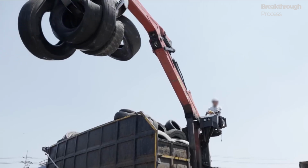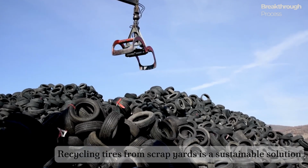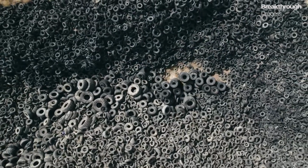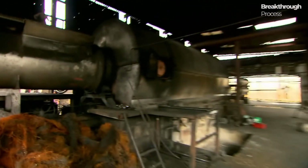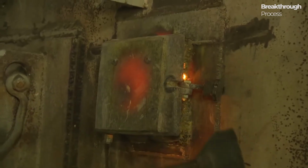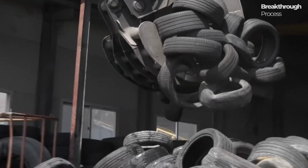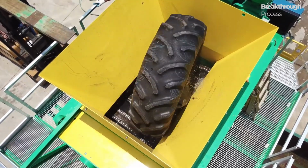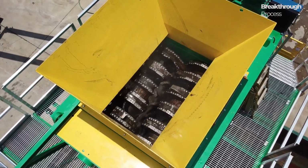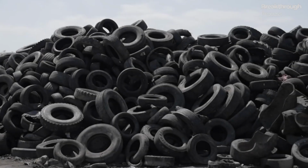Recycling tires into oil is an effective solution to solve this problem, while also creating an alternative source of energy. The process of recycling tires to get oil is mainly based on pyrolysis technology, which is a highly scientific process. Waste tires are collected, cleaned, and shredded to increase efficiency in the processing process. Chopping helps maximize the area exposed to heat.